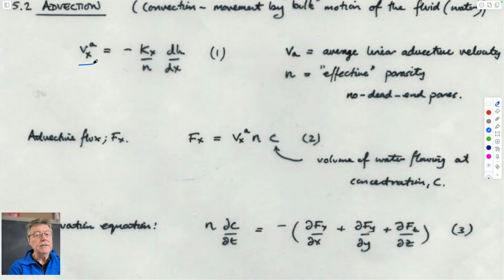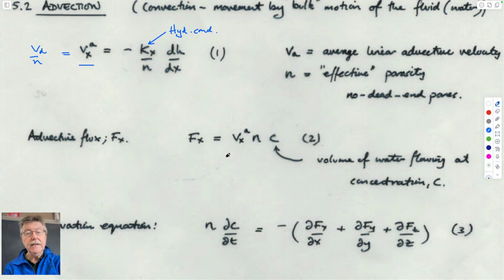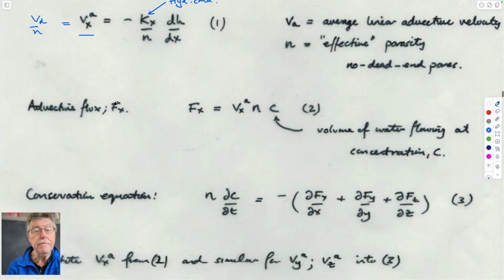If we want to get the advective velocity, we can from the coefficient of permeability. This is hydraulic conductivity, which you know, meters per second, porosity. So this is just equal to Darcy velocity divided by porosity, right? This term here, negative sign. And so we can always get the advective velocity for a system. You can always get that.